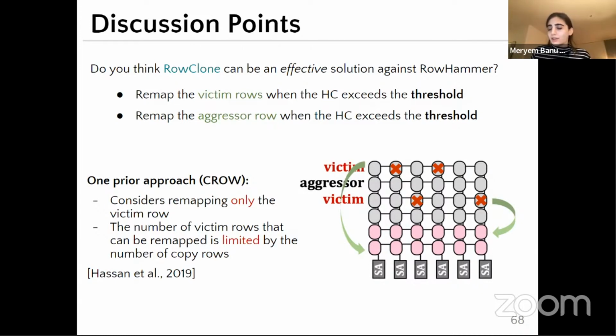I didn't get the question at all. Sorry. Oh, so effectively, you're slowing down your system before anything happens. Yeah, I agree. But I guess that's kind of the case for all the RowHammer mitigation mechanisms, right? You have to somehow slow down the system as you interfere with the system. But do you think the overhead would be higher in this kind of approach? Well, worst case, you have to copy back all of the rows that you have in these copy rows back to the original rows after every refresh, roughly, or whenever you choose to do it, if they're constantly being swapped out.